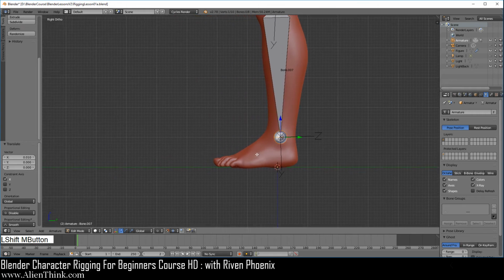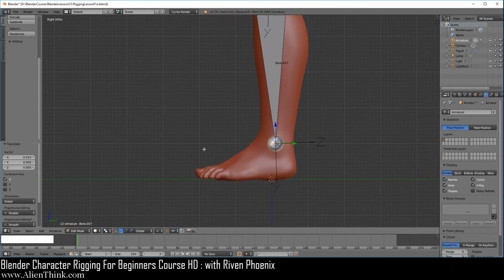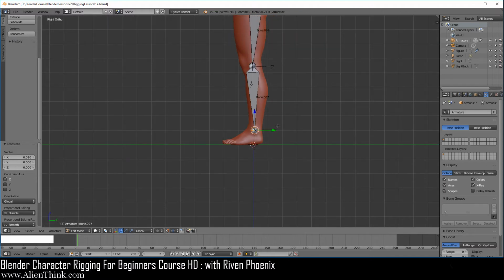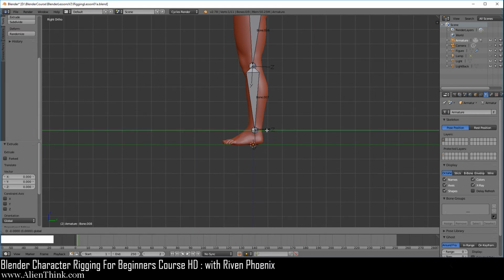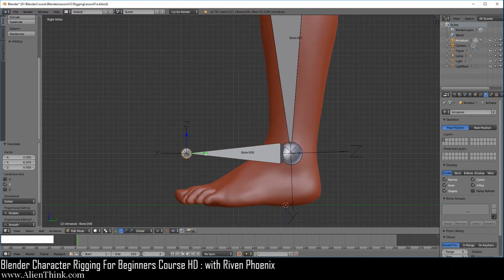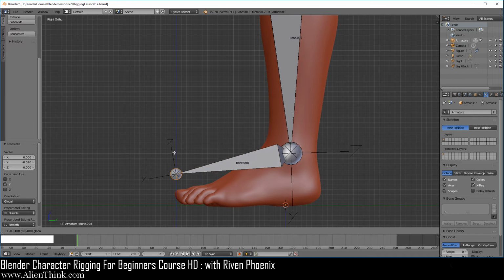Now we're going to create the bone for the foot. We just need to bring it over here and 1 nudge more. So to do this, just zoom out until you get the big grid units. Press the E key to extrude, right click to cancel its movements. Click on this green arrow, take it to the left, 1 and then 2. Now zoom in. Click on this green arrow, take it 1 and then 2. Click on the blue arrow and bring it down, 1, 2, 3, 4, 5, 6, 7, and then 8.